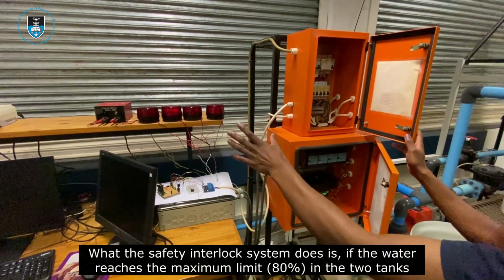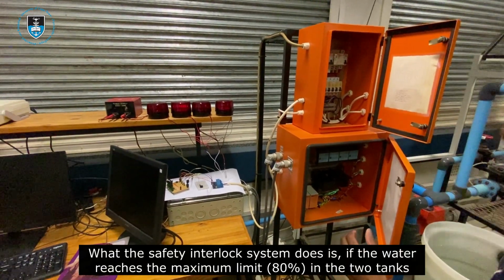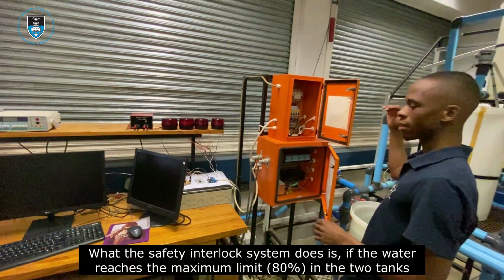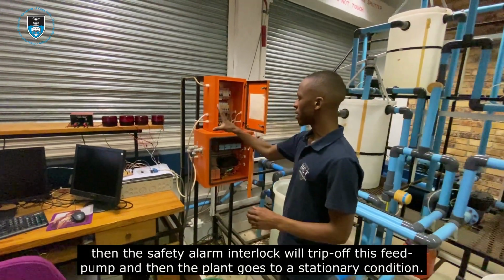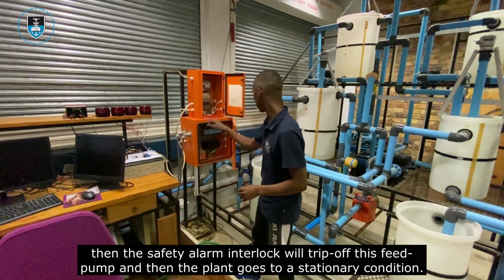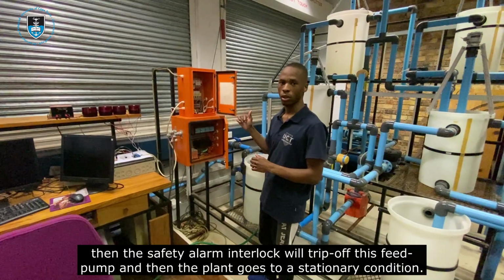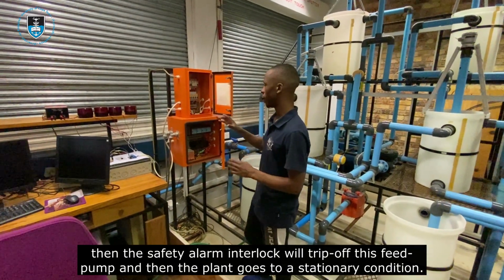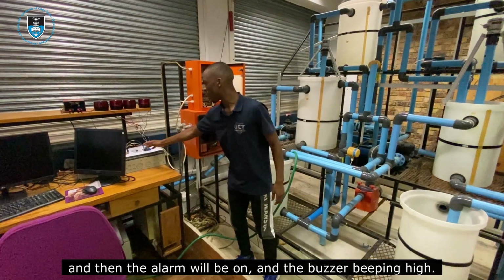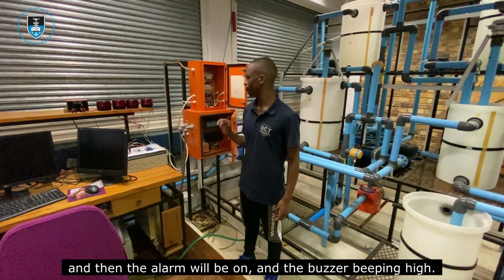Now, what the safety interlock system does is, if the water reaches the maximum limit in the two tanks, then the safety alarm interlock will trip off this feed pump, and the plant goes to a stationary condition, and the alarms will beep, beep, beep, and the buzzer also beeping high.